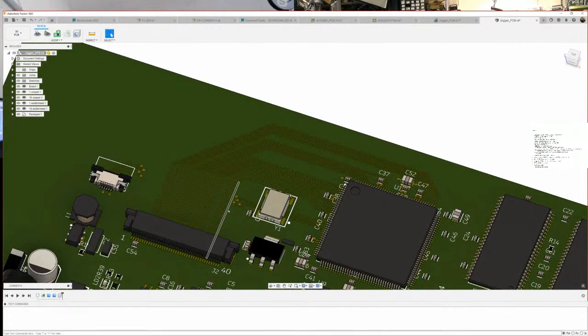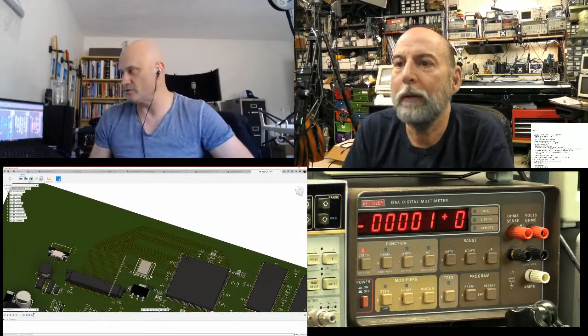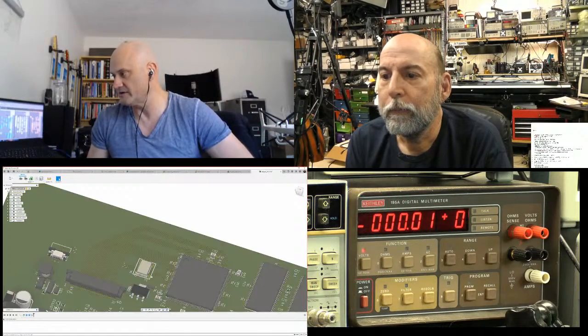And that's precisely what I did. One of the reasons I love FPGAs is your pin out is what you choose it to be, for the most part. There are some special features in FPGA hardware sometimes that require you to use certain pins or groups of pins, but by and large, for general digital I/O, I was able to pin swap all of that to optimize the board routing, and that makes it super easy.